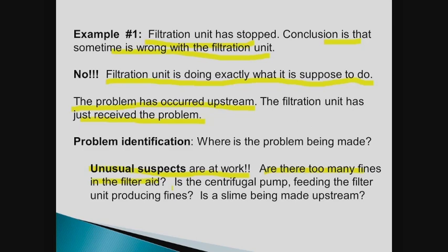When you go ahead and use it, it becomes a filter hindrance because the particle size changed on you. A centrifugal pump was used to feed the filtrate to the filter press. Let's call it a centrifugal pump, but indeed it's actually a hammer mill, a device that breaks up particles. Maybe upstream you have a slime.